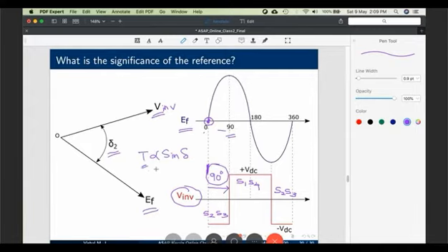So which means if you use such a machine, the best dynamic response is possible, because the machine accelerates with its maximum torque. If it decelerates, it decelerates with the maximum possible torque. Thus, in minimum possible time, you can attain your new speed. Clear? Earlier, due to the delay block, it was taking so much time to reach the steady state. Here, with the least possible time, the machine will accelerate to its new speed. So, it's always best to keep 90 degree.